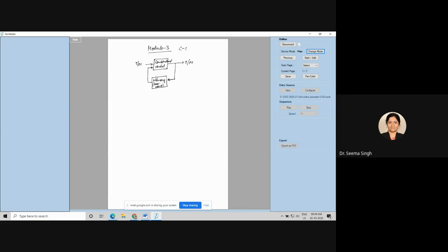So now this circuit will have input, and it will also have the state which is stored in this memory. So this circuit becomes a sequential circuit. A combinational circuit or combinational logic will not have a flip-flop, but a sequential circuit will have flip-flops as well as combinational circuits. A sequential circuit cannot be complete without the combinational circuits in it. This is the basic block diagram of a sequential circuit, which shows that memory is coming into the picture, and memory only is the sequential component, and the combinational circuit will have combinational components.